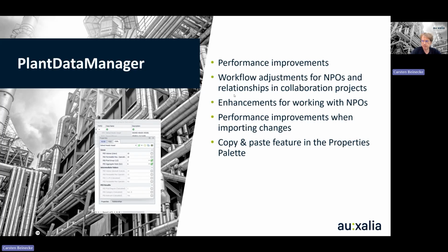Then in Plant Data Manager, we have a feature which we call not placed objects, or here NPOs. And NPOs allow you to create an object in Plant Data Manager which is not in the drawing. And there are 2 typical use cases. One is create a not placed object, for example, a pump. And you create a pump, and you can define all the values, all the properties, you can give it a tag. And you then can later decide, do you want to insert that pump later into a drawing, or do you want to keep it only in the database for reporting, for example?